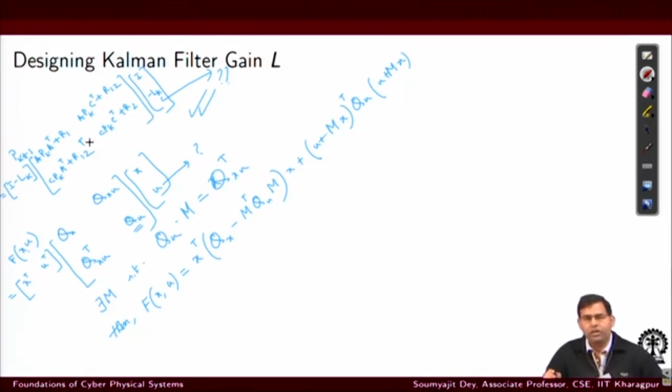Now, we want to figure out what is the value of the Kalman gain such that this variance of the reconstruction error would get minimized. As we can see, this dynamical equation tells me how the variance in the kth step can help me compute the variance in the k plus 1th step. In that way I get a recurrent relation, and that gives me a series of values of pk, and I can see how these variances evolve. Now, I want to tell how that will be minimized.